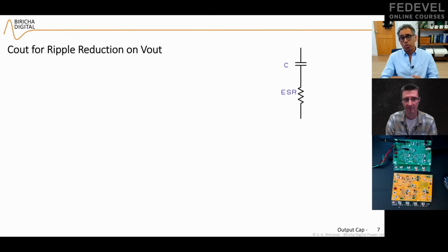For example, point of load power supply, the low voltage, high current power supplies that have to react very fast. Let's say you are feeding an FPGA or you're feeding a big microprocessor, are typically ceramics, right? And therefore, you do the calculations for the ripple based on the ceramic equations. And I'm going to show you one in a minute.